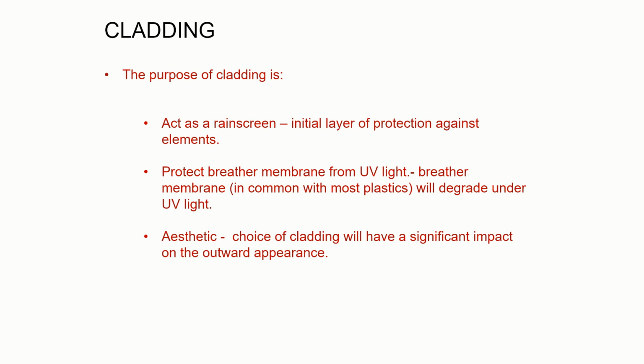So what do we have cladding for? Why do we need it? Initially, it needs to act as a rain screen. So it's the first layer of protection against the elements. And by rain screen, we mean something that stops the snow and the rain hitting the construction inside. It's probably not 100% weather tight, but it's enough to be able to prevent the kind of driving rain